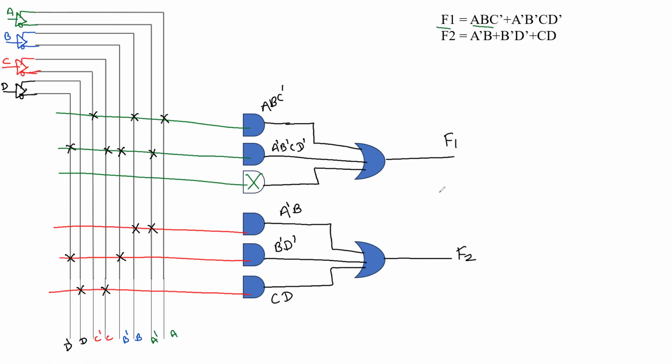Whereas in the case of PAL, only the AND array is programmable, and the OR array is not programmable. Here product terms cannot be shared with another function. That's why, if repetition of product terms occurs, we have to use new AND gates. So like this, we are able to realize PROM, PLA, and PAL. Later we can summarize again. On the basis of that, whatever function is given, we can do this. So thank you.